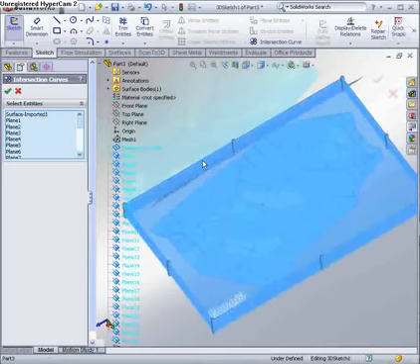Then we can use this to create a drawing, export to a DXF. It could go off if you were making a scale model to a profile cutter, to make it like a little landscape model, or we could use the surface and create a solid, make some geometry changes and see the volume that we need to cut out to build whatever structure we need to put in there, a host of other applications that we could do.